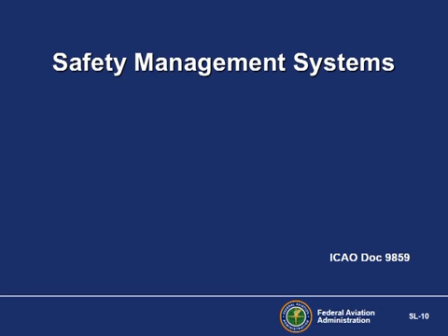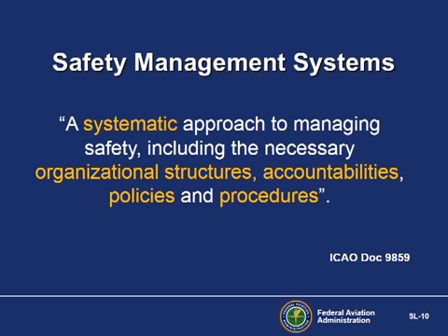Now let's look at ICAO's definition of a safety management system. ICAO defines SMS as a systematic approach to managing safety. This refers to looking at systems and managing those systems. In other words, we don't want to look at just the pilot. We also want to look at pilot training, pilot checking, pilot manuals, chief pilots, operations managers, fleet managers, the entire system that supports the pilot. This same principle is then applied to all sectors of the service provider's operations. In summary, SMS is the application of business management practices to the management of safety.